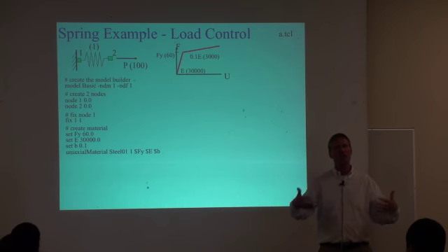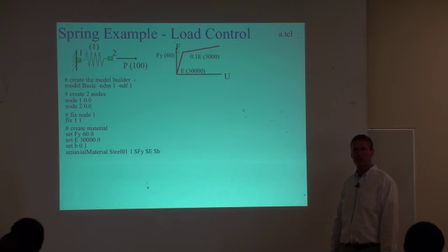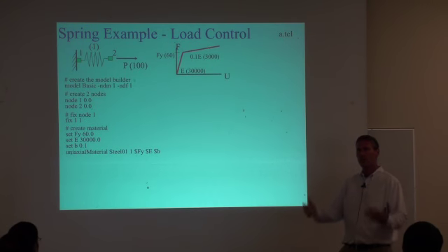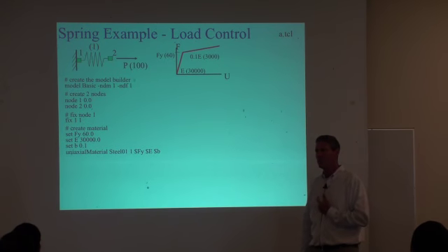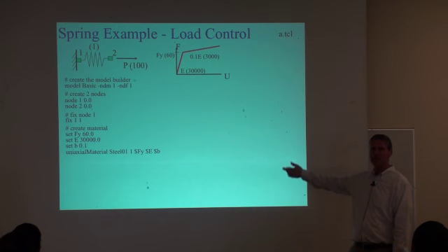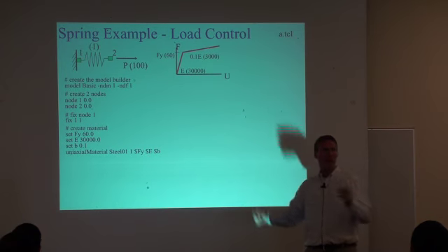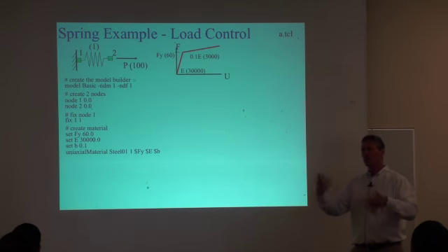The nice thing about using these variables is that you actually get to see what they correspond to. So sometime later, if you forgot what the arguments for steel are, if you've written a script like that, here's where I change E. I don't need to go back to the command manual to figure out which particular argument happens to be E. So variables are useful in describing different things.